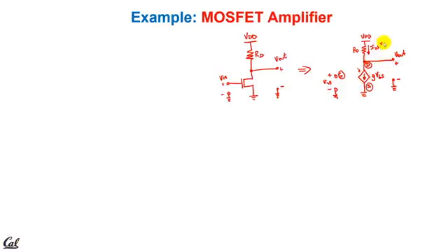This is going to be equal to G times VGS. There'll be a voltage across that resistor. So V of RD is going to be what? Well, it's going to be the current flowing through the resistor times its resistance. Exactly. Now, by KVL, what's V out? V out is going to have to be VDD minus that drop across the resistor. You can all at home do this, because VDD is the distance between ground and up here, and so V out must be that minus whatever this drop is. That's a perfect KVL.